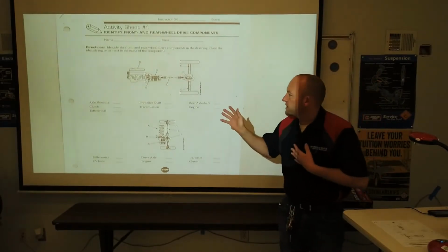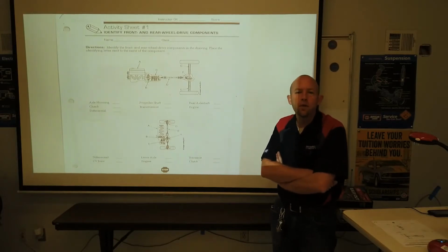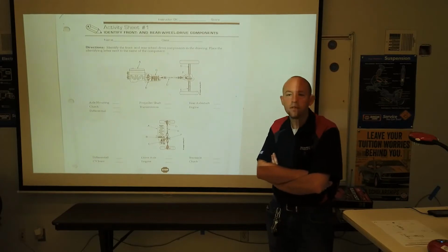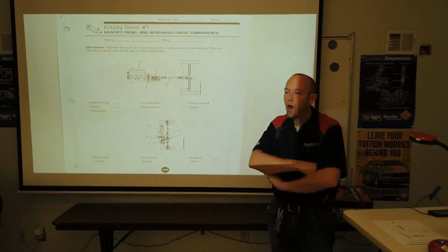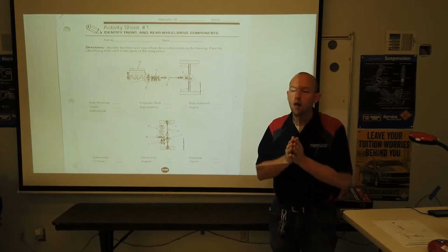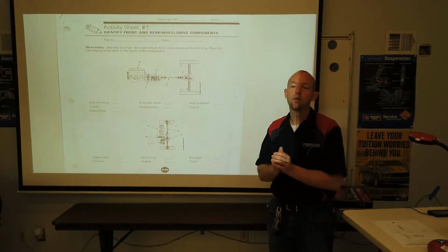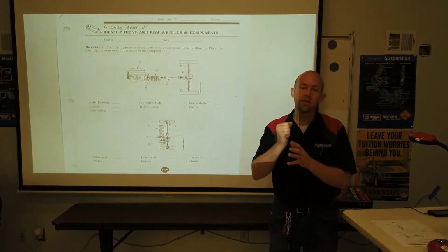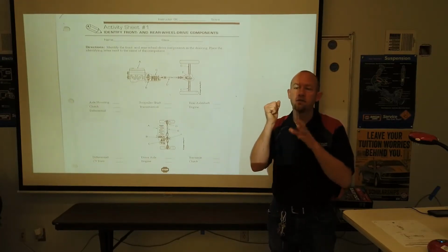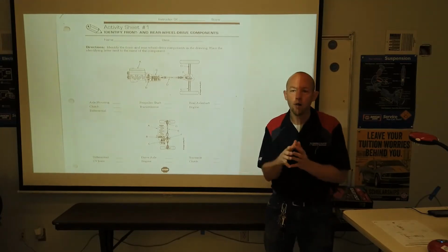I'll start by saying that the style of engine that we use in the automotive industry is referred to as an internal combustion engine. We had that conversation back when we talked about chapter 1 and we talked about our 4-stroke cycle, where we have on our intake stroke the pistons moving down and the intake valves open, we're bringing in an air-fuel mixture. The compression stroke, the pistons moving up and the intake valve would be closed, and we'll compress that air-fuel mixture down to a really small volume.